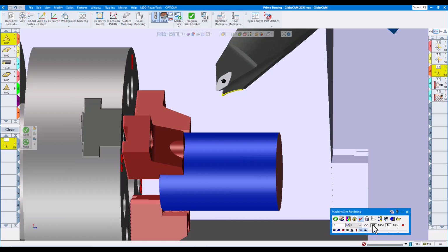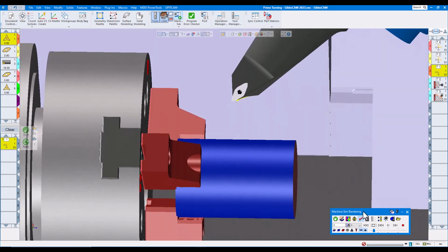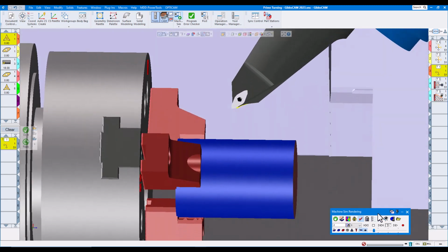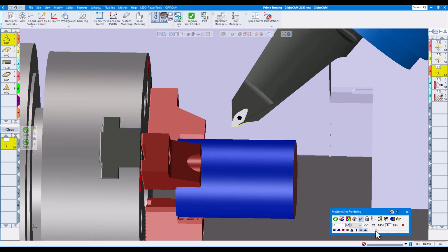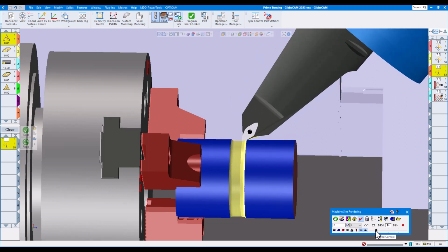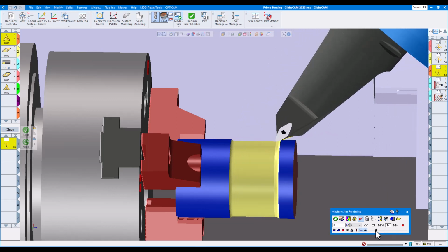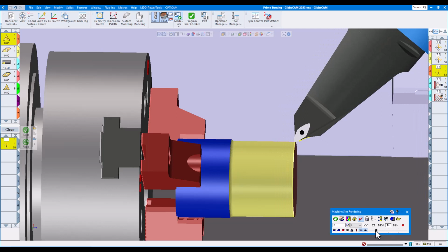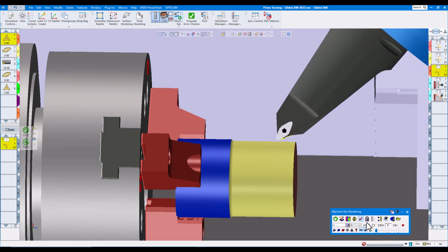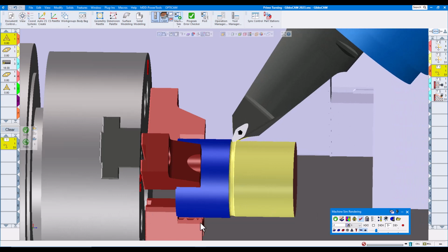So this time we have kind of a combo tool here with 2 sides on there. And the tool path, you really don't plunge into the part, you always do an arc. And when you're coming off the part, you're doing the same thing.